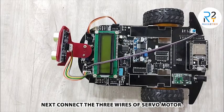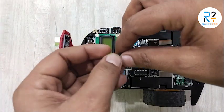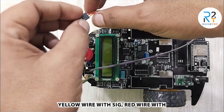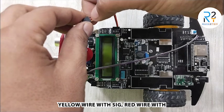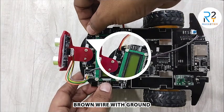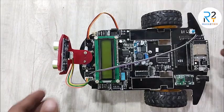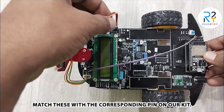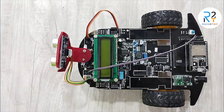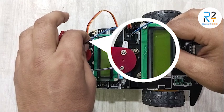Next, connect the 3 wires of the servo motor. These are the wires of the servo motor. Yellow wire with SIG, red wire with VCC and brown wire with ground. Match these with the corresponding pins on our kit. Then connect the signal pin to D15, SIG pin to D15.